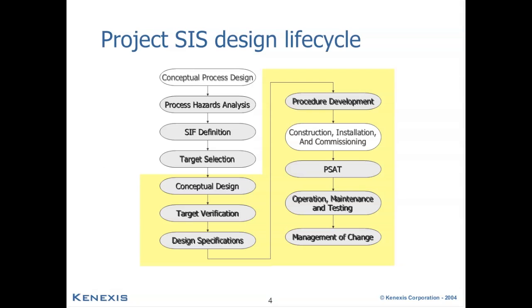Within the SIS design lifecycle, once again, the verification phase typically occurs after selecting your SILs for your given functions within the safety instrument system and prior to the development of your specifications and your procedures. What we'll look to establish in this phase is take the SILs obtained from SIL selection and then determine if the safety instrument system is capable of meeting the requirements set forth within the SIL selection portion of the process.